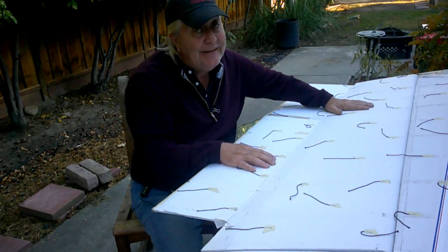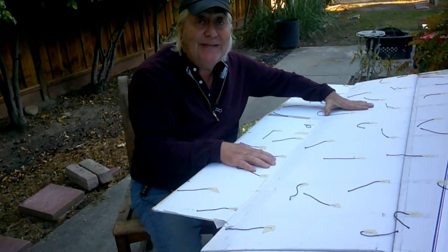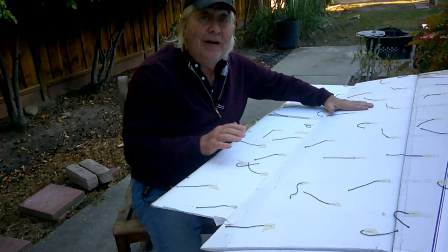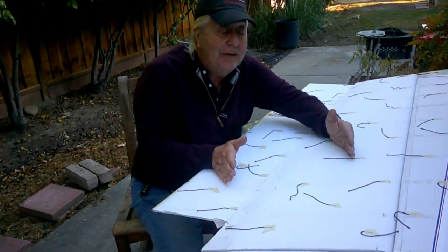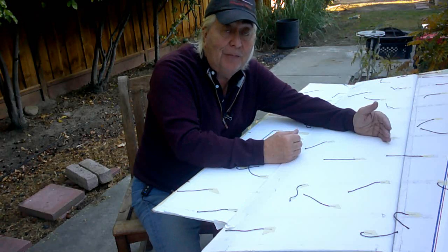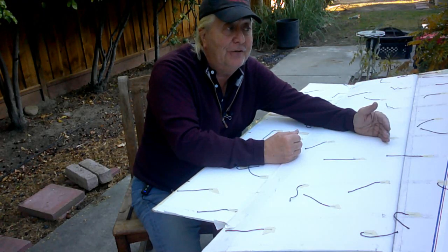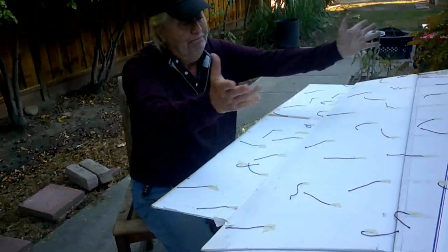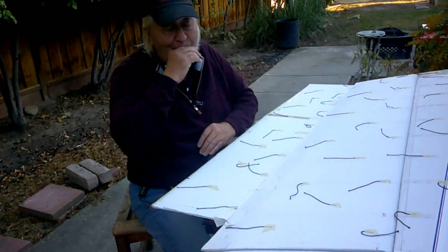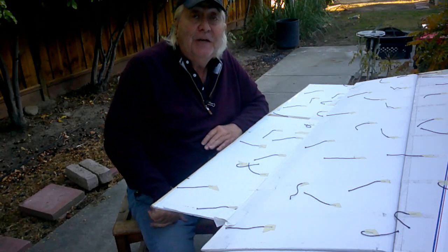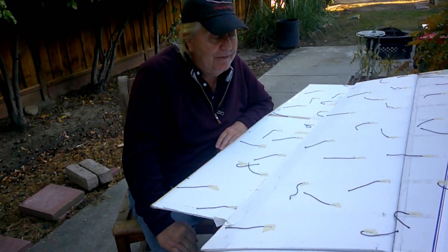Not that they planned it that way, but it just worked out peachy. So even though they have the really small chord, they don't have the laminar separation bubble problem because they're tripping the flow with a very inefficient vortex generator. But it works great. Cuts into your performance, but it makes for a very flyable aircraft.